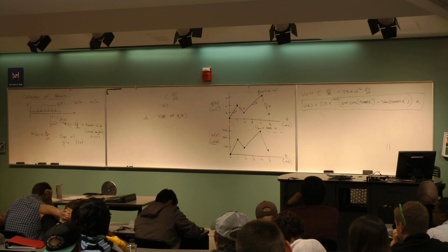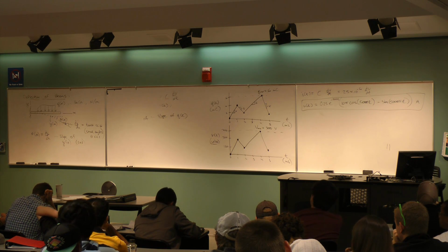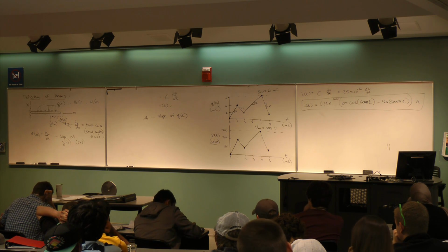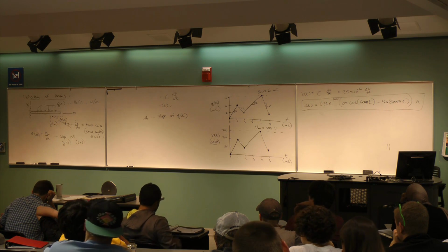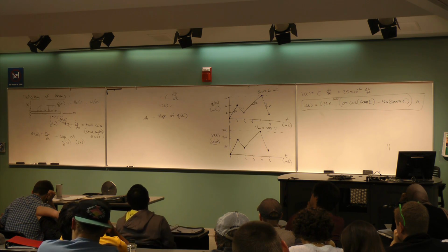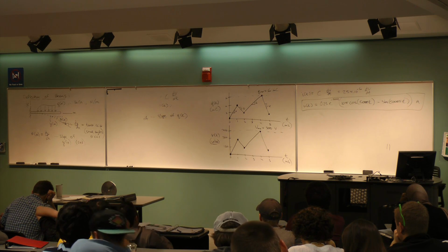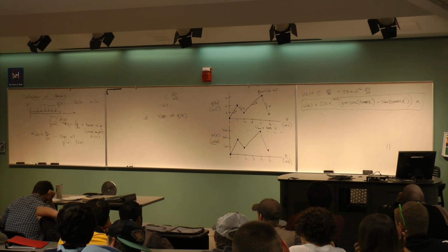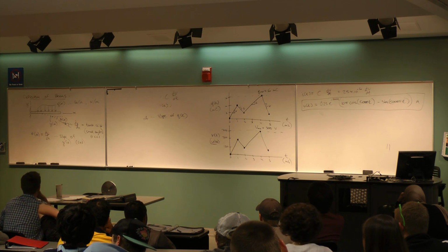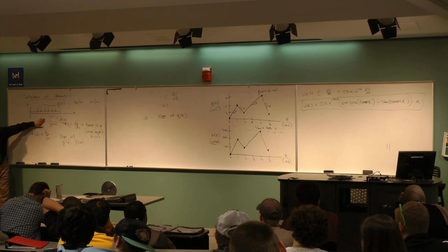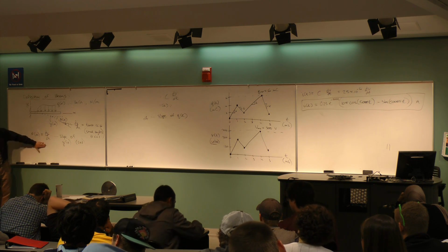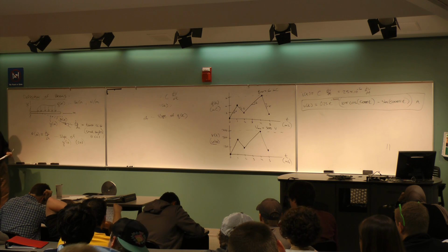And a deformation of that shaft, because it has loads on it, we can use beam deflection theory for that. And I'm worried about things like how much the angle changes, not just the deflection itself, because this thing's got to fit. It's got to rotate nice in the bearings. If I get too much slope at the bearings, then I can damage the bearings themselves. So all these kind of things are important. So I'm interested in the deformation itself. I'm interested in the slope of the deformation at certain points, okay?